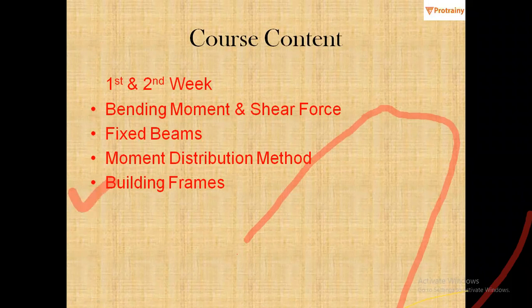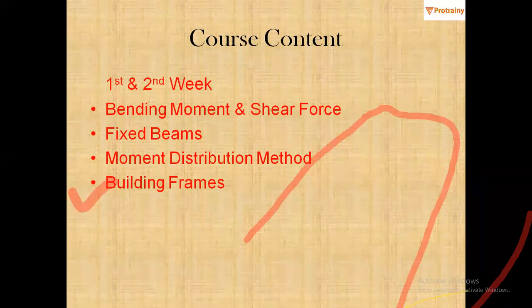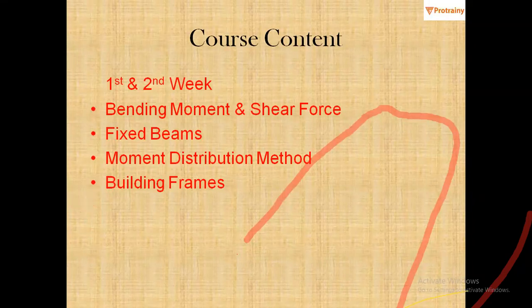Then comes moment distribution method. When it comes to manual methods, there is slope deflection, there is double integration, then there is moment distribution, and other methods as well. But moment distribution method is widely used. It is tried and true. So that is why we have included it. You can use it for a single continuous beam, or a single fixed beam, or for portals, multi-story portals. So this is frames.